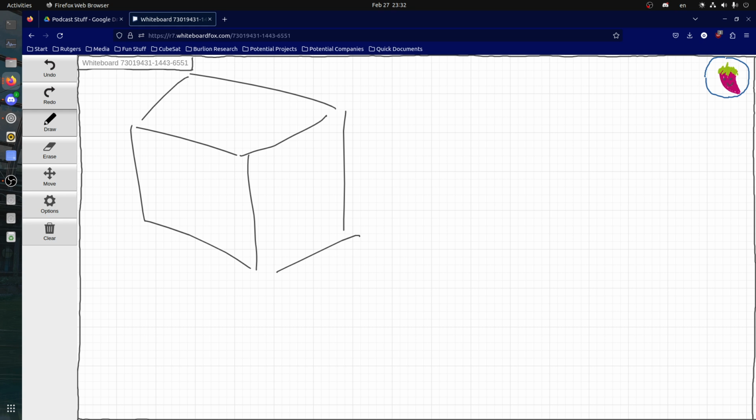So yeah. Oh, one major benefit of magnetorquers is that there's no moving parts. In a cold gas thruster, you have to open a valve. That's a moving part. In a reaction wheel, there's a literal spinning wheel. That's a moving part. All of those are sources of error. A magnetorquer has no moving parts. It's just a coil of wire with electricity running through it. So it's a lot more reliable, you could say, in the face of mechanical fatigue or anything. Or rather, it's fairly easy to design around it. So yeah, that's the magnetorquer.